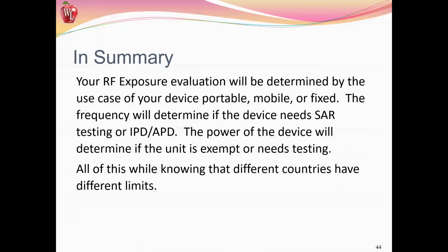In summary, your evaluation is going to be determined by the use case of your device. Is it portable, mobile, fixed? The frequency is going to determine whether you need SAR, IPD, APD, or different MPE requirements. The power of the device is going to determine whether you're exempt or you need testing. And you need to look at all of these requirements while knowing that different countries have different limits.